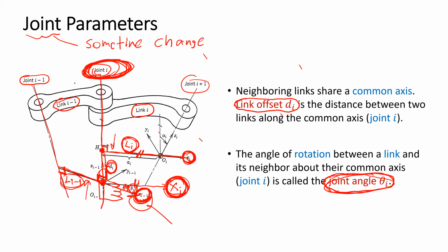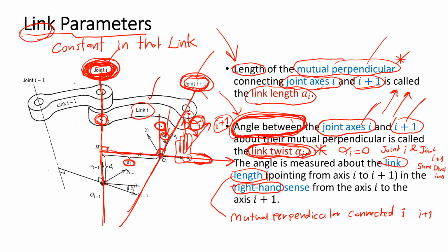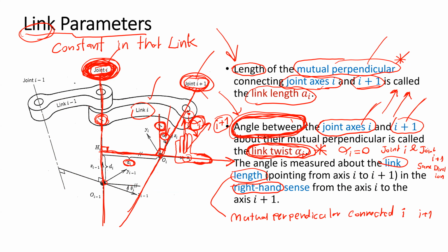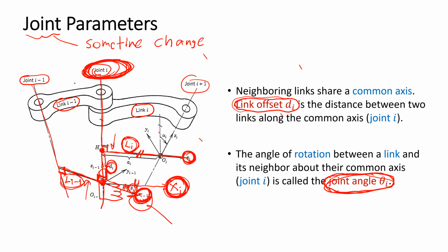Before this, in these two slides, we introduced the 4 parameters describing a link of a robot. Without talking about the frame that we attach on the link, we just introduced the physical meaning of the link length, link width, offset, and the joint angle.